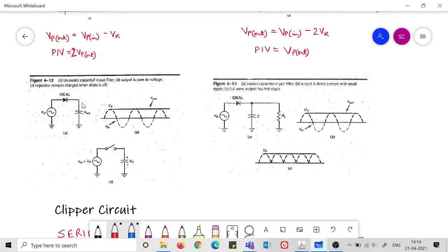So the capacitor stays in the voltage of Vp. So in this situation, this Vp will be constantly maintained in the output. So you get a very nice DC voltage in this case. Okay, so this is one configuration in which you can get a constant DC voltage of value Vp. So please note the value also here. It is not 0.318 Vp, but it is Vp directly.